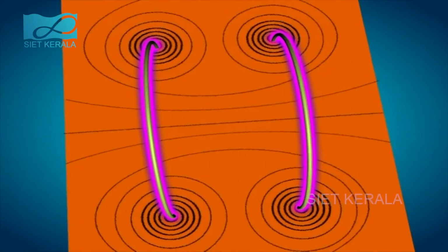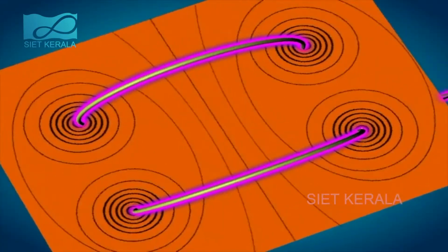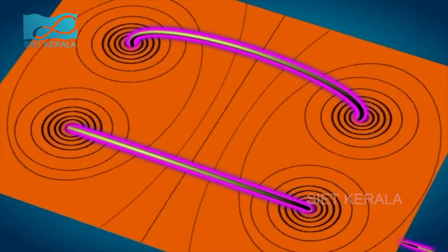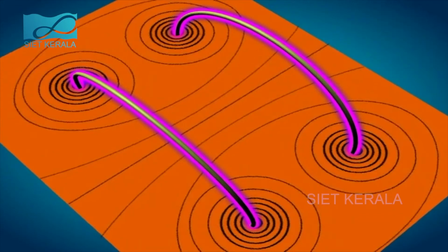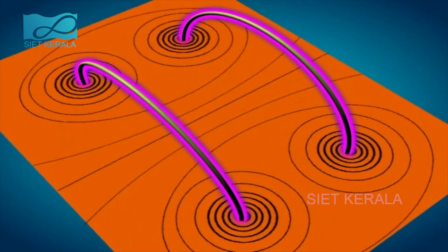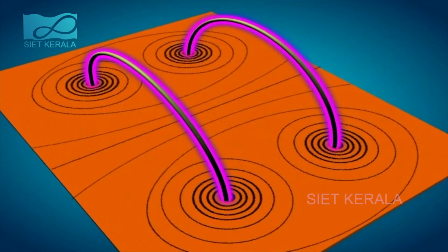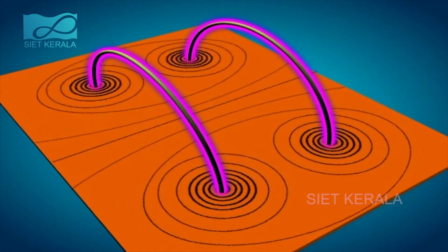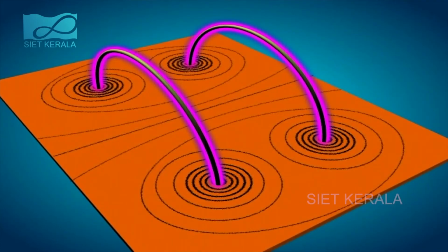This line is perpendicular to the plane of the coil. The direction of the lines of force depends on the direction of the flow of current through the coil. Make 2 turns of the same wire in circles, not touching each other, and repeat the experiments. Let us see the direction of the magnetic field around each coil. Very near to the coil, circular flux lines are formed around each coil.